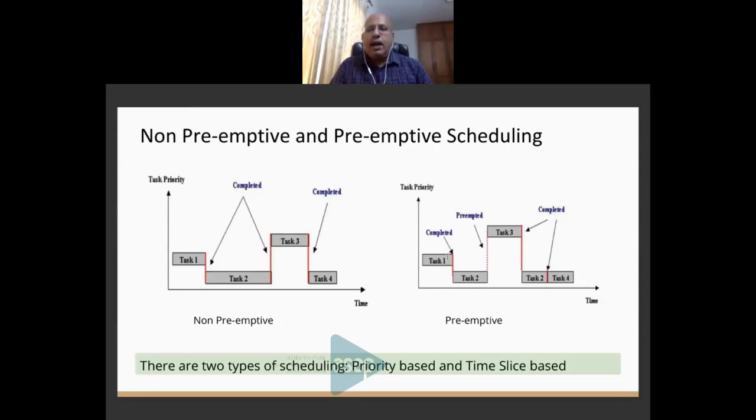That means in a hard real-time system, as I told you, suppose some braking event came. That will result in an interrupt service routine, and that interrupt service routine will schedule a new task like task 3, and immediately a task switch has to happen to task 3. Because if you wait for task 2 to complete and then schedule task 3, by that time the aircraft will be down. So we need to use a preemptive scheduler in hard real-time systems, because you get an instant response to high priority threats or high priority tasks. So that is what you are seeing there.